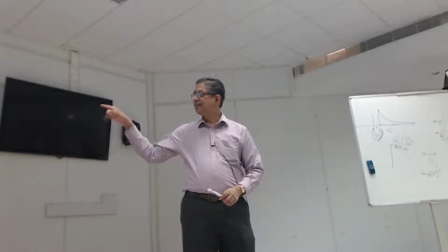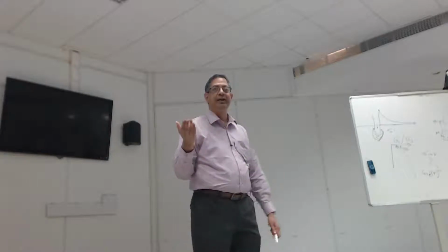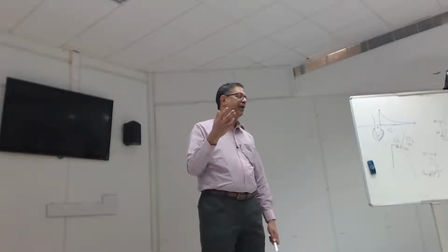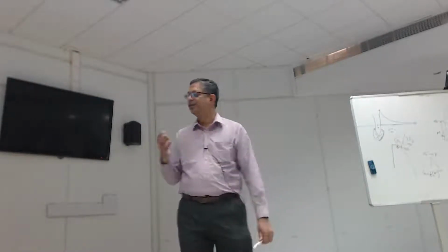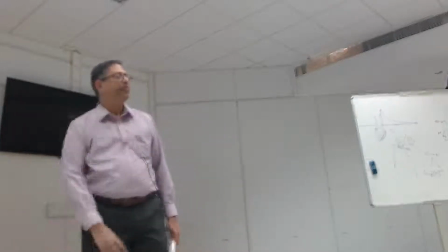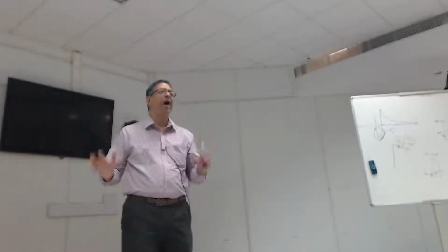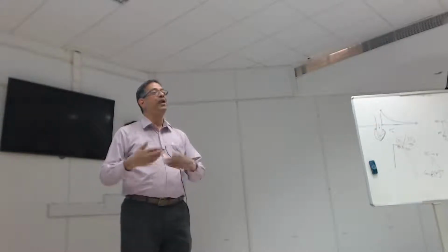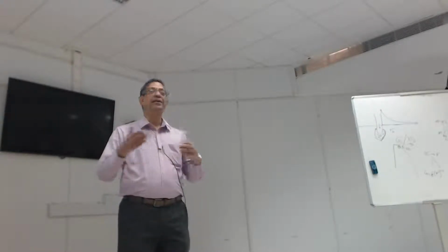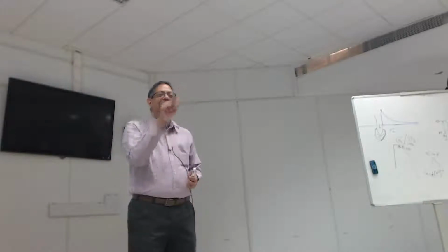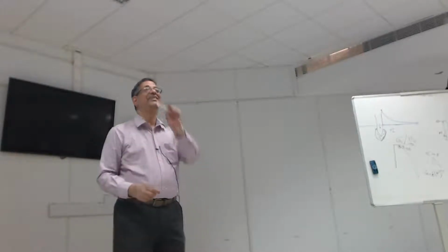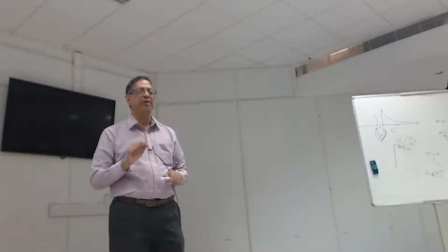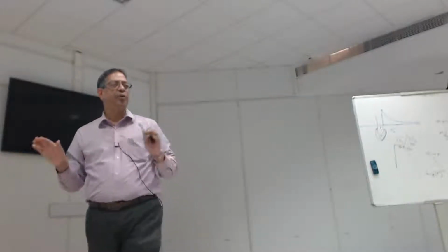So this comes from Eurocode 8, and other codes as well. Why should I just pick on the Europeans for this? But somehow the people who developed these expressions ran numerical analysis, and in computer code you can select Young's modulus wherever you like. So they selected it there, with no justification for this at all, other than that the early research has used that.